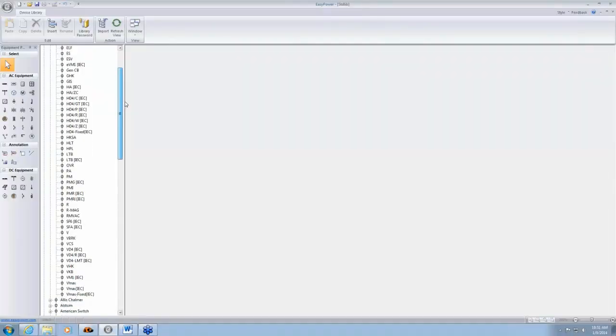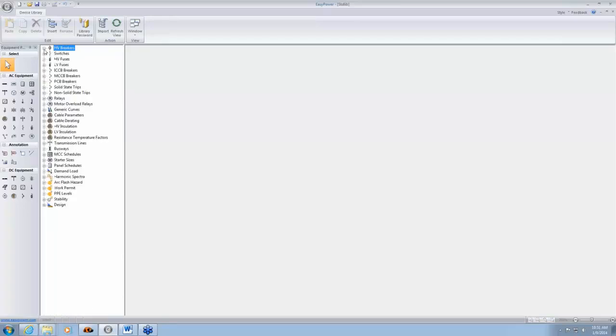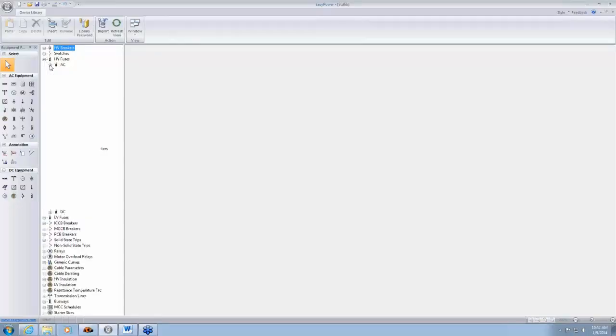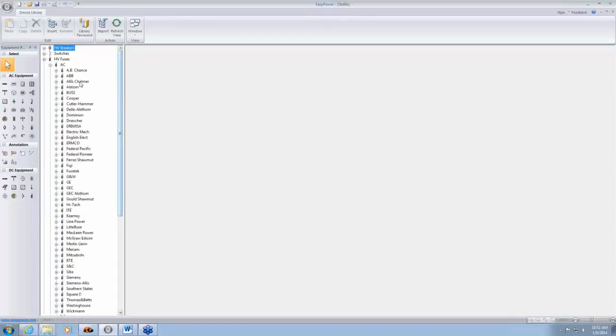High voltage circuit breakers don't have curves associated with them, but the relay that has a trip curve, once it's time to trip, sends a signal to the circuit breaker to open up the circuit. That's what high voltage breakers do, that is, obey the command of the relays. Then fuses, we've got lots of different manufacturers and lots of different types there.